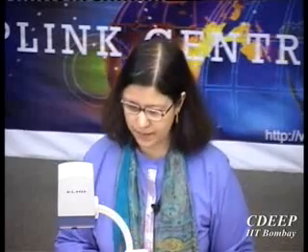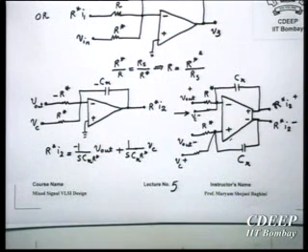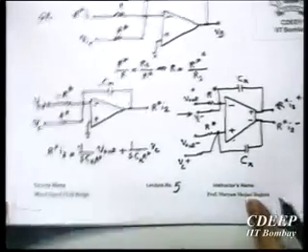One more thing is because you have two signals of having 180-degree phase shift, you will be able to omit even harmonics. Whatever even harmonics you have will be omitted. Therefore, it will give better linearity. But the only problem is now number of components will be twice. So this is the price with it. So trade-off with performance and error. And of course, if we want to get a single-ended output, at the end we have to convert it to a single-ended output.